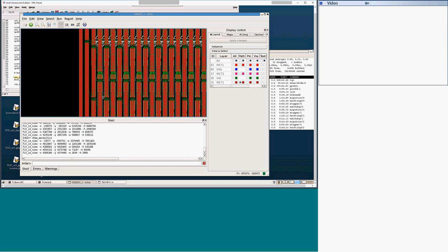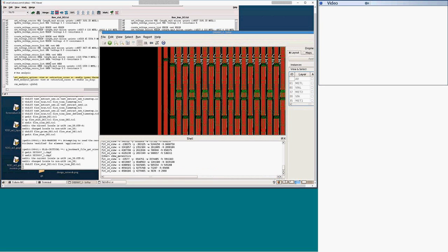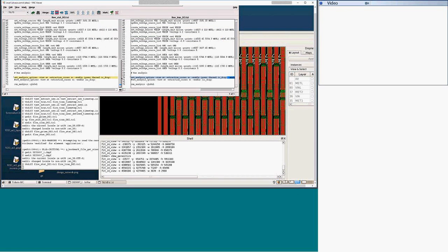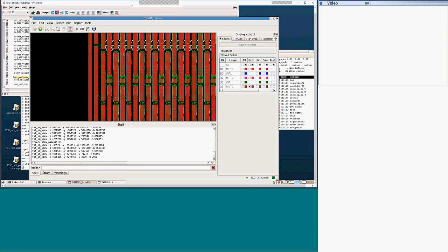And you do not extract poly resistance, right? So that's why there's no poly layer shown to the right. You see, in the layer map there is no poly. Right. The design itself has poly data. The SPF has poly resistance data. We did not read layout on poly, and we do not display it because we skip poly layers in the layer map, because we are looking for IR drop from metal 1 to metal L.